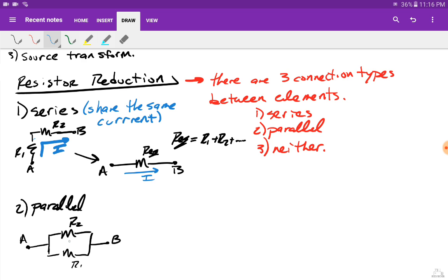Now, another way to think about the parallel connection. That was one definition. The second is not a definition, but a consequence of the definition. Whatever's between the same two nodes is in parallel. Voltage sits between nodes. There's a voltage between A and B. And since everything is between A and B, everything has to have that same voltage. Everything in parallel shares the same voltage. So basically, if the series connection is the current connection, then the parallel connection is the voltage connection. Current connection, voltage connection.